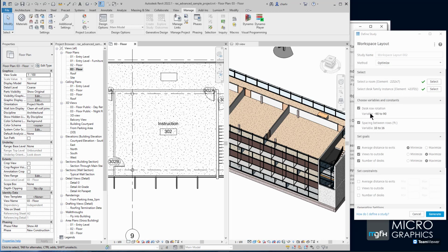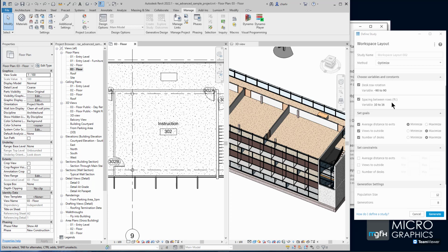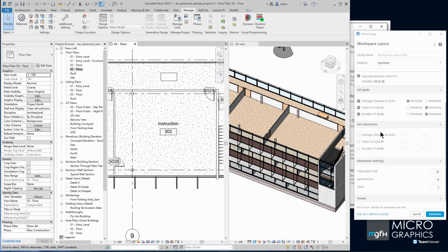All right, so there are some variables. It can be rotated however you want. There's some spacing. These are now in feet, so 10 feet, nearly 3 meters, that sort of thing. Right, there's no switch to meters here. That's defined in the Dynamo script. So if you want to change it to meters, you need to just open the Dynamo script, and in there alter the values. Right, regenerate the script, and then you've converted to meters. Right, that's obviously a different discussion.